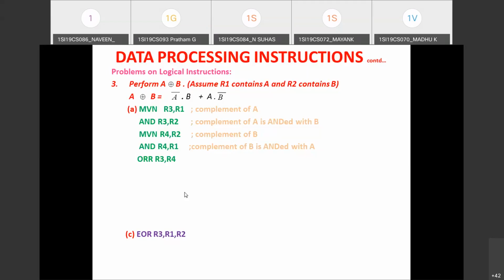As you told, the bit clear instruction can also be used. What it does is it first inverts and then performs an AND operation. So I can calculate each of these terms with a single instruction. See how to do it? BIC R3, R2, R1. See what it will do? It inverts R1, takes the complement of R1, and performs an AND operation with R2.